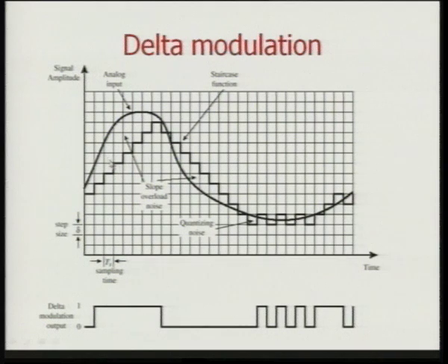Again the next value is higher, so again the value continues to be 1. The same thing continues until we come to this part where you find that the signal is increasing, and after this point the signal starts decreasing. So, when the signal starts decreasing out here, you can see that the value now becomes 0. Again the next value is lower than the previous value, so the output continues to be 0. The same thing continues until this point.